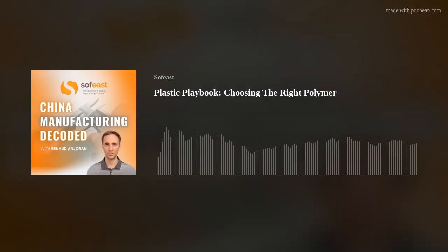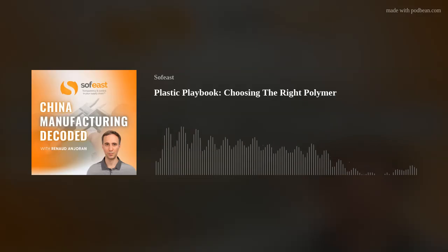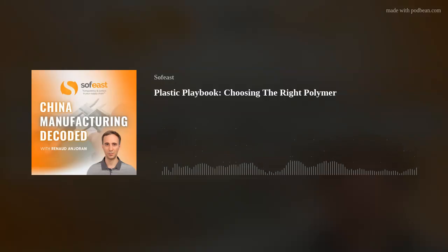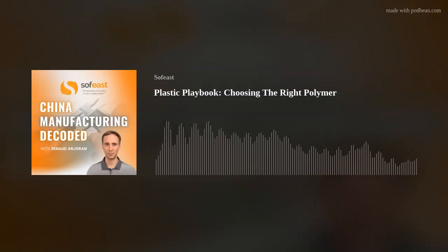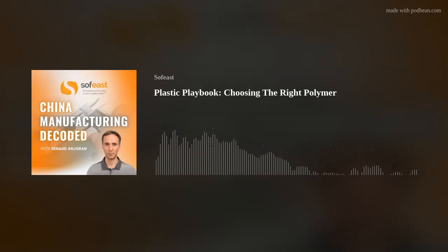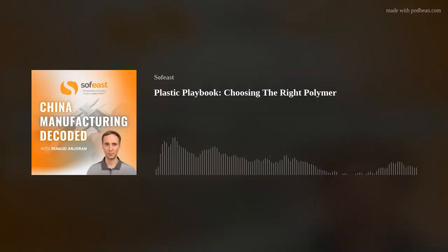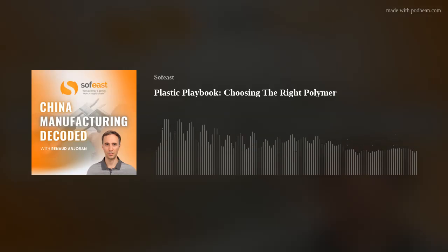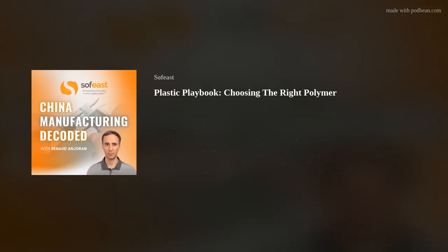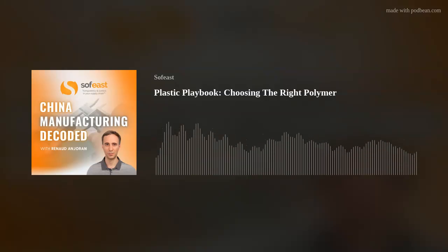And again, we can actually modify nylon with a number of different additives. And I think the biggest one that is used, or most commonly used, is glass fiber. Now, with the glass fiber additive, this makes it even stiffer, stronger, potentially the wear resistance will come down a bit because it's more fibrous. But yeah, glass fiber is a very, very common additive to make the general baseline of the nylon's properties be improved or increased. Which is great. Right, let's move on to the next one.